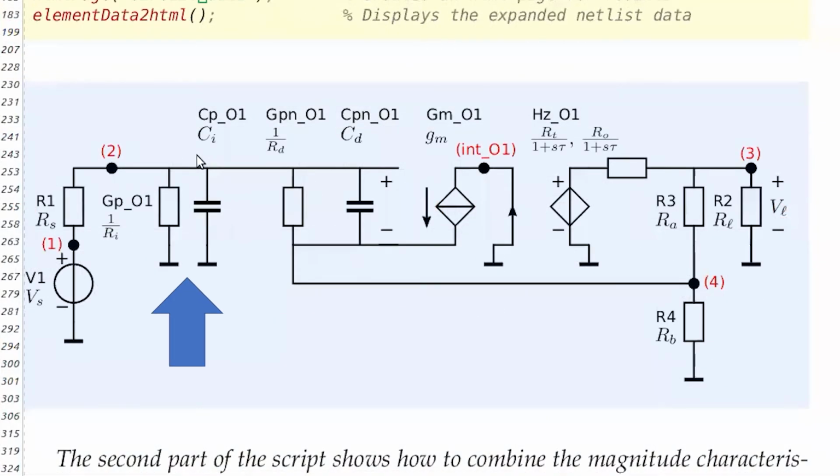So we can just put this circuit in Slicap for evaluation, and we want to see the effect of the parallel connection on the asymptotic gain. And that is what we expect. We expect that there will be an effect, because if we select H1 as reference variable, then the controller behaves as a nuller, except for this part.